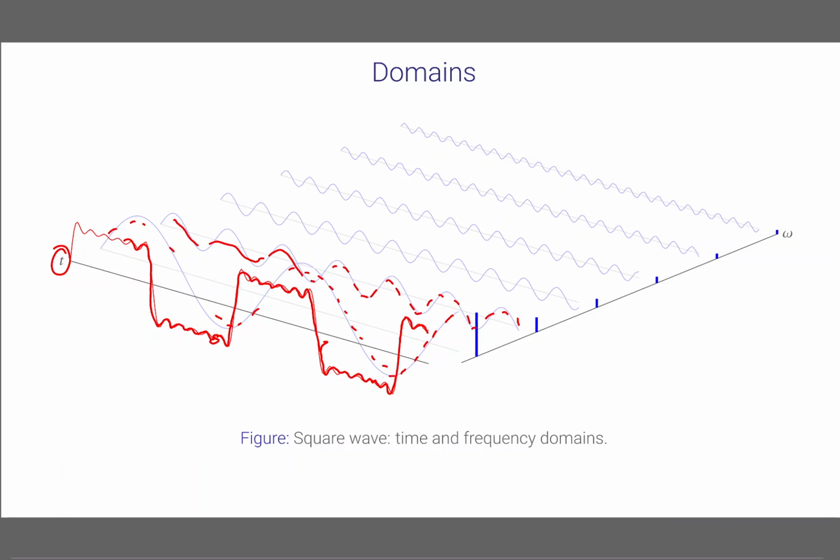But you can see this second sinusoid is of higher frequency than the first one. Actually it's twice, then the third sinusoid, the fourth sinusoid, and so on. But the amplitude of each of these sinusoids becomes smaller and smaller. So we have drawn the amplitude of the first sinusoid, the amplitude of the second sinusoid. Amplitude means the height of the third sinusoid, fourth, fifth, and so on. But they are at different frequencies. So omega naught, 2 omega naught, 3 omega naught, and so on. So don't take these numbers to be literal. They are multiples of omega naught. So the addition of these different sinusoids gives rise to this rectangular signal, and we can represent them with these heights of the sinusoids that we have drawn, and that is actually the frequency domain.